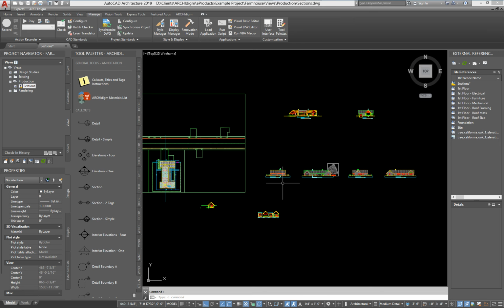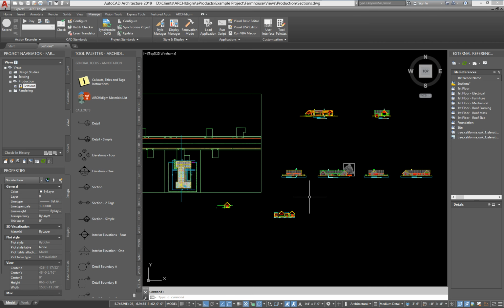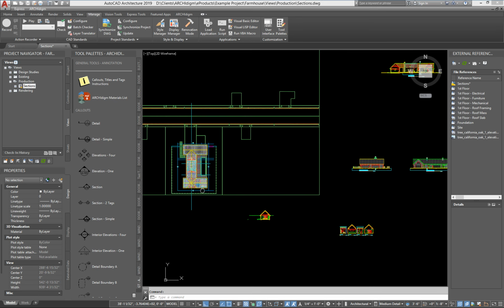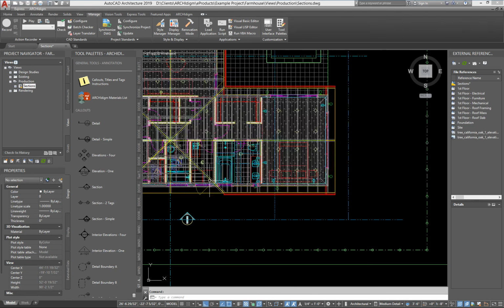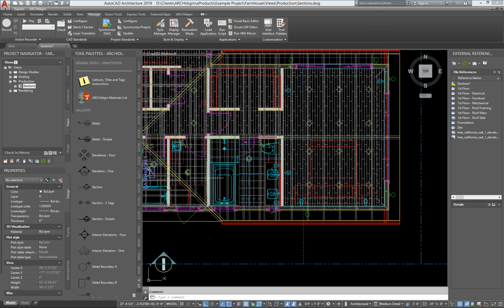It helps me be more productive, I think, because I can work with all of these things in a single file, where I like to have them together to do cross-referencing and copying of annotation and so on. But what I'm going to focus on really here is just the annotation symbol and its relationship to the sheet that those interior elevations go to. You know, how the automated numbering and the linking of that numbering works. That's what I will focus on. So here's the area that I'm planning to do the elevations in.